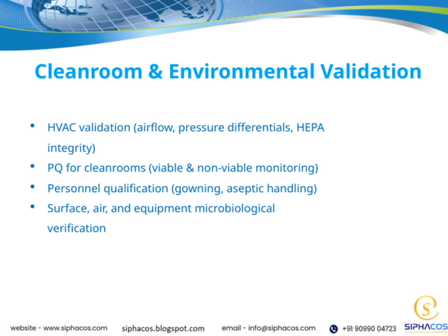Personnel qualification is another vital component. Proper gowning procedures and aseptic handling techniques are fundamental to prevent introducing contaminants. Ensuring staff are well-trained and qualified directly impacts the overall integrity of the cleanroom. We also perform microbiological verification on surfaces, air, and equipment.